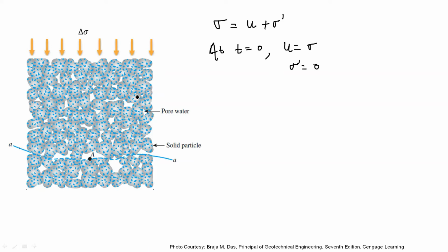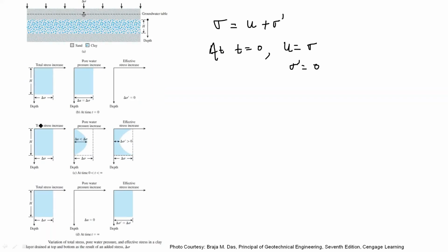Due to the squeezing out of the pore water from the soil solids, the consolidation takes place and that is called primary consolidation. So here you can see in the figure, in the primary consolidation time, what happens? The pore water keeps decreasing. Why? Due to squeezing out of the pore water. So in this time, the pore water keeps decreasing and effective stress keeps increasing proportionally.